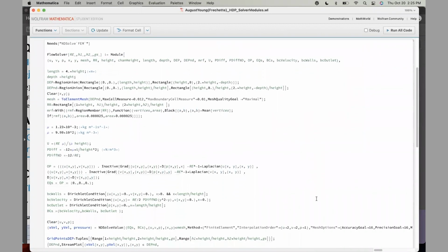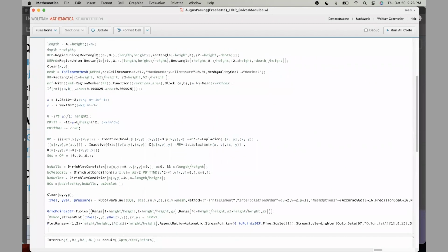This is like one Navier-Stokes equation, like you are working with a substantial chunk of code. So this is our flow solver that I talked about right here. All I'm doing is setting up the region, and I'm applying a mesh to that region, and I'm defining that refinement region that I wanted to use to be able to really zoom in on that separatrix.